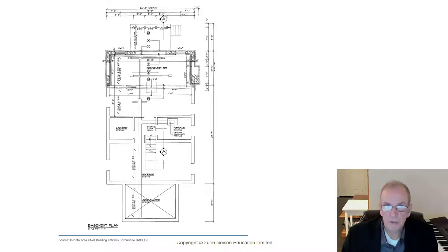So much like the new construction that we've looked at in the Brook drawings and other drawings, that would be supported on a steel column that would be coming across. It would have a steel plate welded to the top of it. And the joists are running in this direction, and they would run into this wood beam. They would be on joist hangers going into the wood beam.